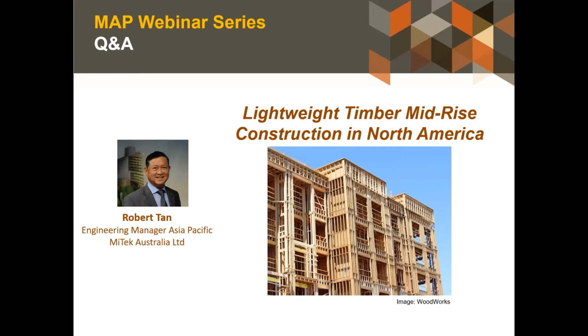Another question here from Polo. What are the typical performances and optimal uses of the different wall bracing systems that you showed? Okay, bracing systems. The truss system with the metal webs is fairly light. It wouldn't provide the greatest forces. The plywood would be the most common because it's highly rigid and highly stiff. So you'll see the truss one, for example, at the very top story where it's a lighter performance. You wouldn't see that in the lower story.